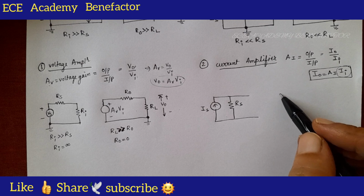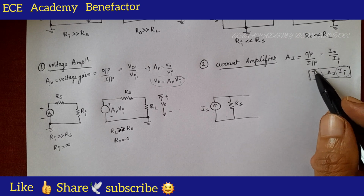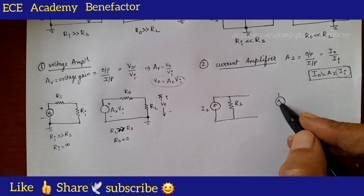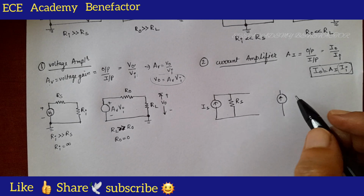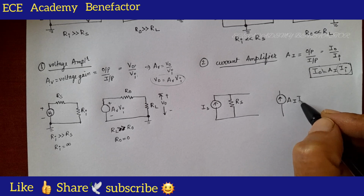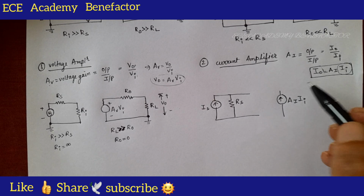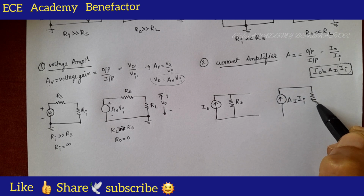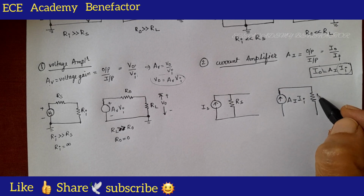And at the output circuit, what we need to place? A current generator. So, we place a current generator, this one. What should be this value? Its value is AI times of II. As there is a current generator, we need to use one resistor R naught in parallel.